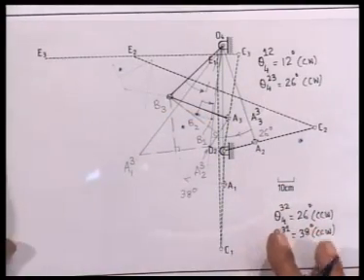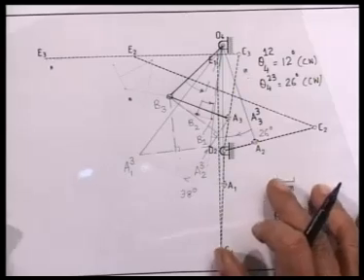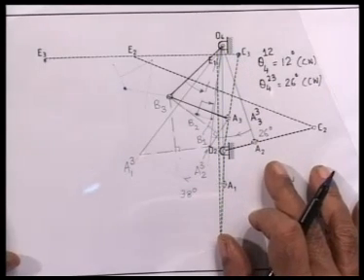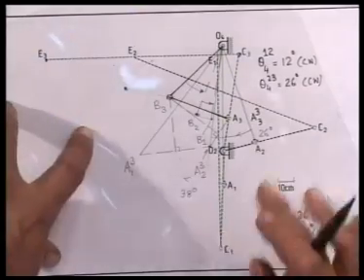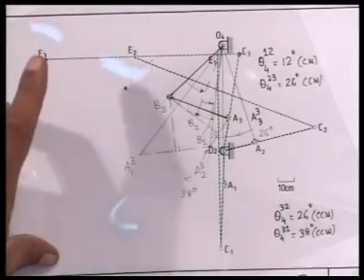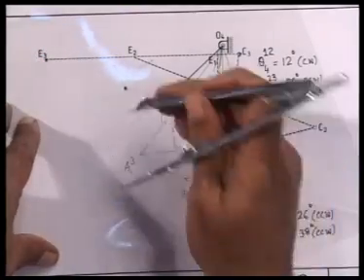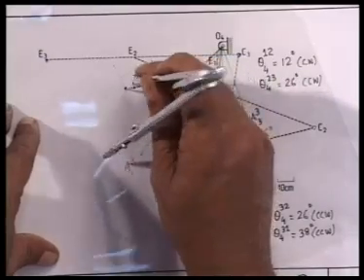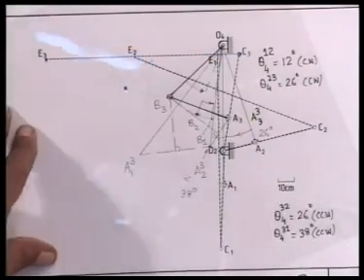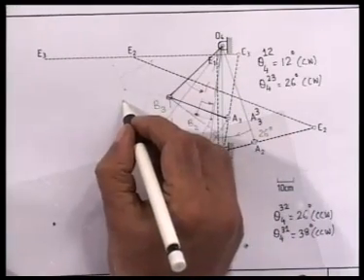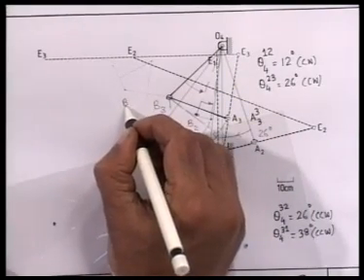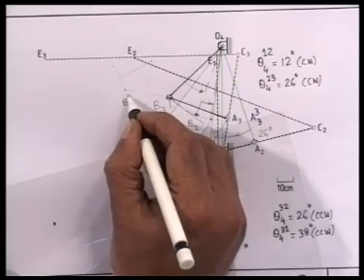If the door board is held fixed in its third configuration, then C2 is made to coincide with C3 and E2 with E3, and wherever B2 goes, this point I mark on my drawing sheet. This is B2 inverted on the third position.